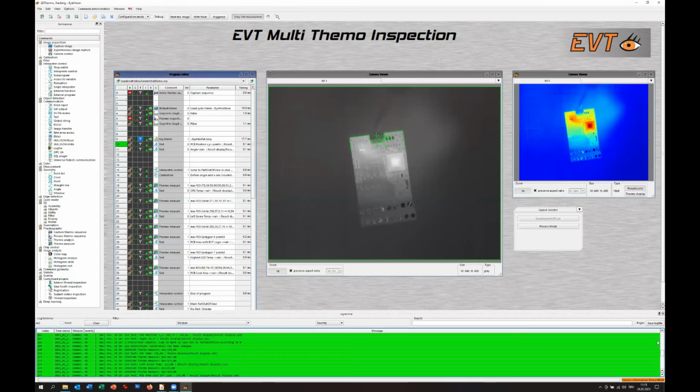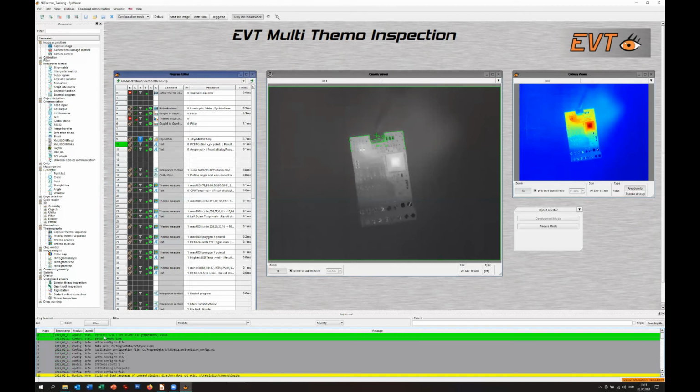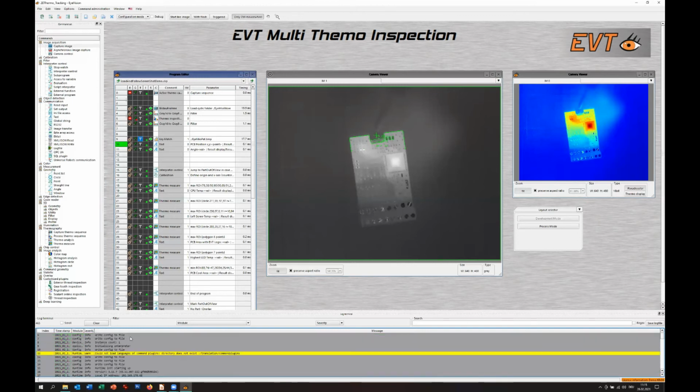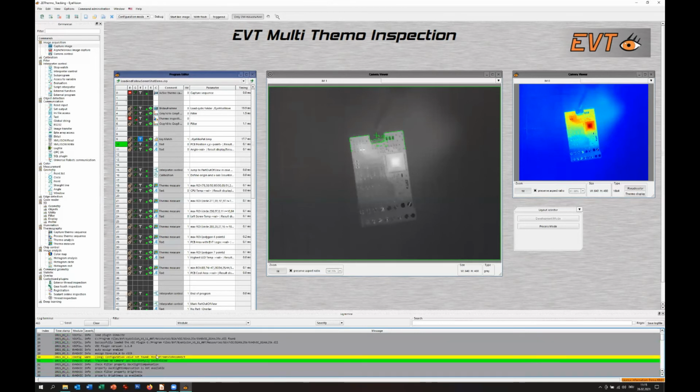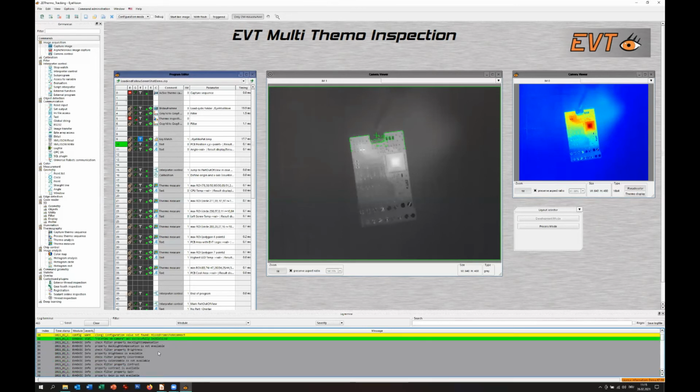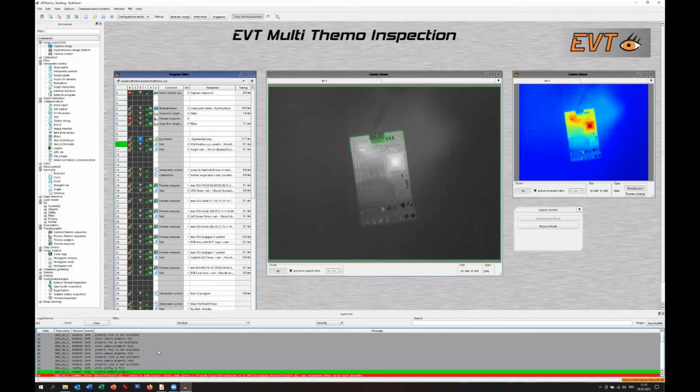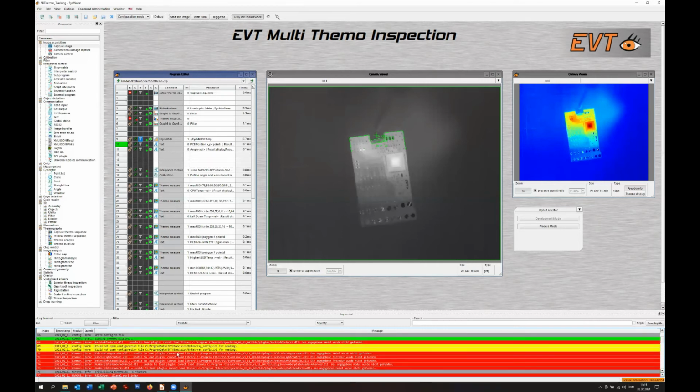And that's why it's also important for us, because first of all, we can see what software versions you are using. But the boot-up section is also very nice, because you see here if everything initialized well or if something is missing. For example, this is my preferred example. Once I had a backup IO module here, and for some reason I simply removed it. But because I only removed it without telling the software it's no longer there, the software tries to activate it, and it says, okay, it's no longer there.